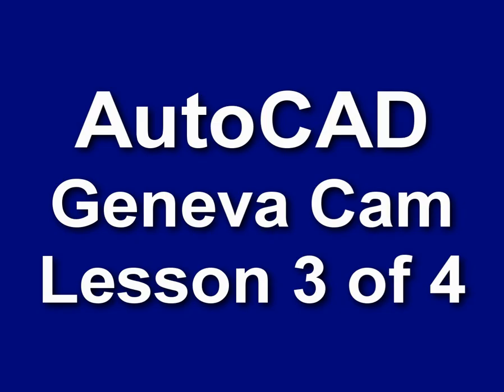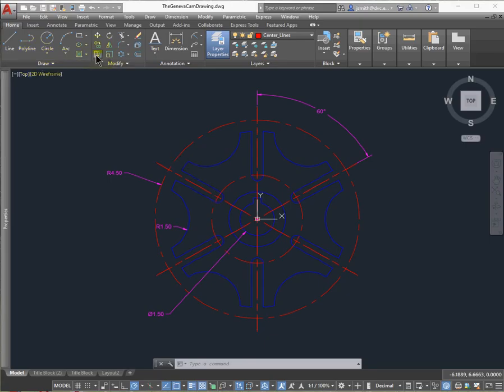In this lesson, we're going to continue building the cam and dimensioning it. So let's go ahead and type in 0, 0. And what we're doing is we're still building, this is the center line. So I've put it in the center here. So I'm on the layer for the center line, and it's in red, so that's how I know that's in the right layer, and now obviously I see the center line. All right, so now I need to do a couple things here.